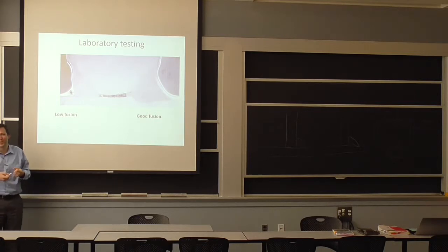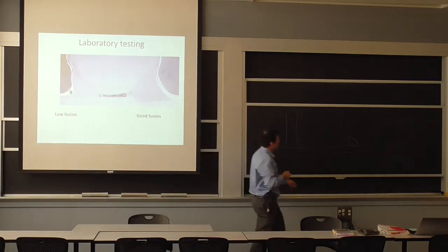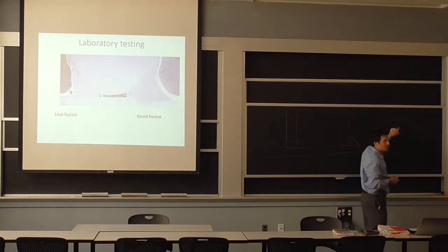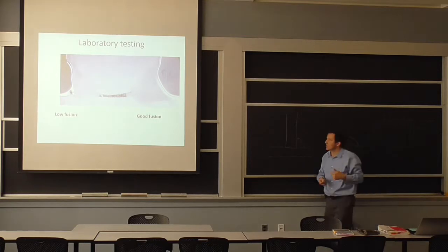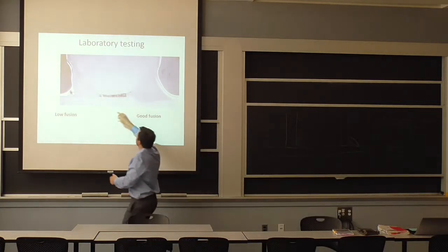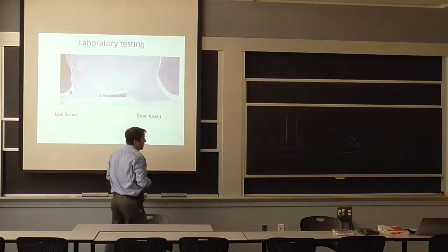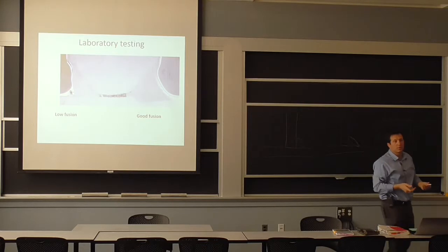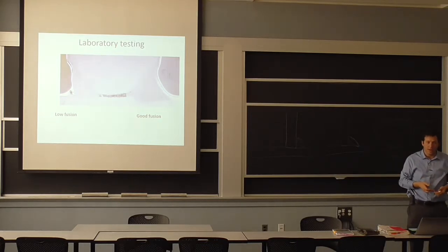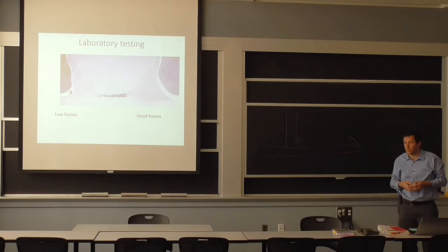So what the process is there is you can still tolerate, because you've got so many of these joints, right? You have one here, you have another one there, you have so many of them. So the idea that you have one bad weld on one side, because these are all working together, this one and this one, the bar is running this way, is acceptable. But it does become a question of proportion. How many of these are you going to tolerate? And if we were in the shop, seriously, you just ask the guy to redo this one, and next time he's going to pay more attention, probably even do it himself.